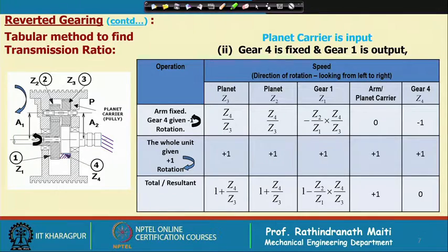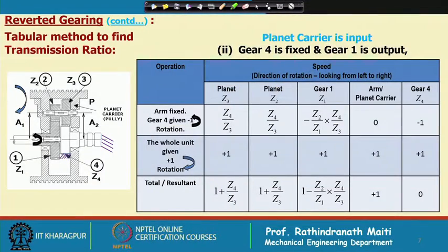Now, in the normal case we can brake it and hold it for some specific purpose, but if you would like to use this unit as a differential gear unit, in that case one will not be held, but will turn. So, if it is on the inside, it will need more torque to rotate. So, it will almost remain stationary, the other one will rotate and we will get the differential action.